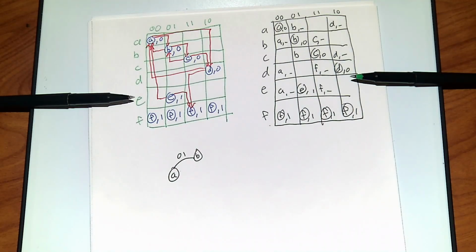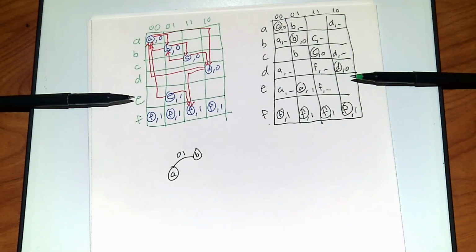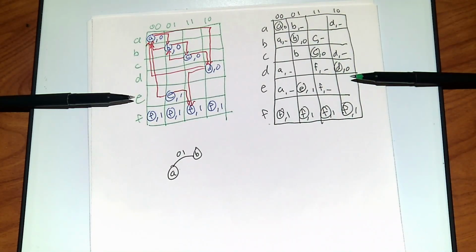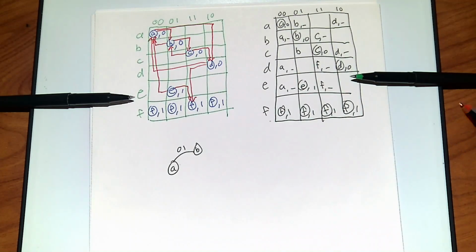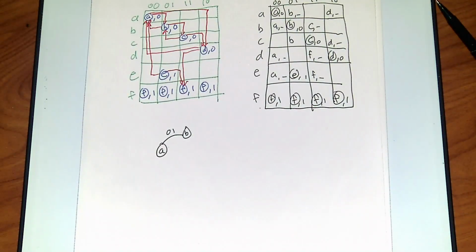Okay? So the next thing we want to do is to see, do I need all of these states? Now we've coded what they want, how can we handle it? And if you remember, what was our basic condition to say two states could be merged? Two states can be merged if you start in one room, go to the next room, and say, wow, this looks exactly the same. You can't tell from looking on the outside where you were by any sequence of inputs. So if I'm in two different rooms and you will never tell which one I was in, then it didn't matter which one you were in.